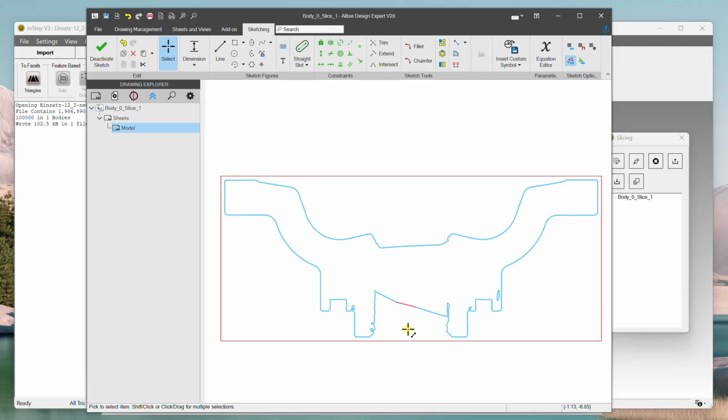Maybe recreate where this axis passes through, because like you can see, some of these are not very clear. So you may want to use, halfway between this side and this side, create an axis, and then pick whichever side is better, rotate around that axis to generate your original body again. That's generally the best way I can recommend doing these kinds of things.